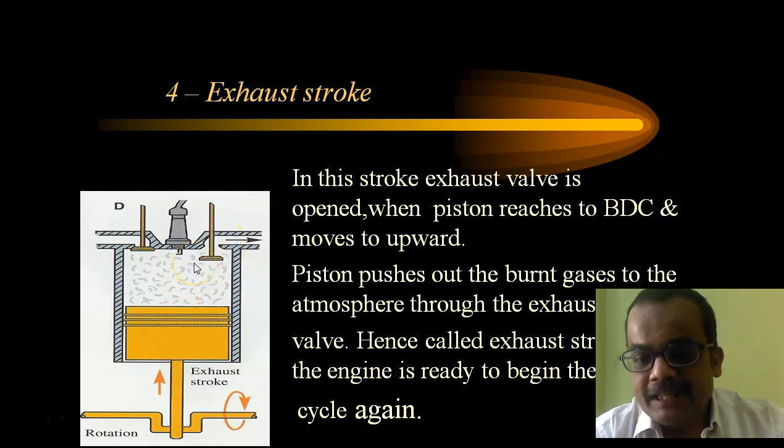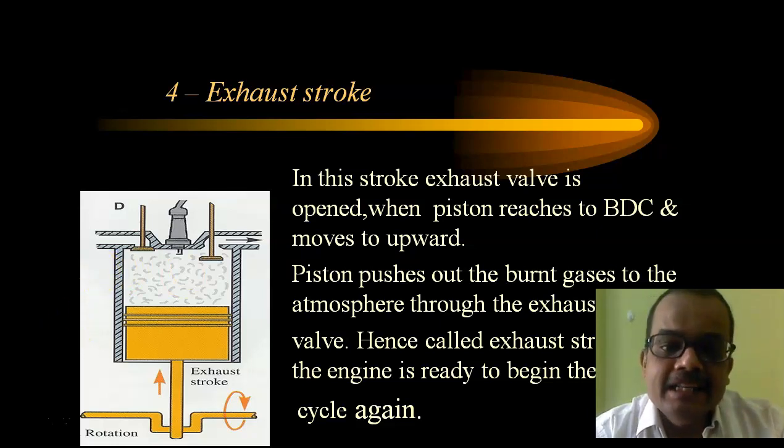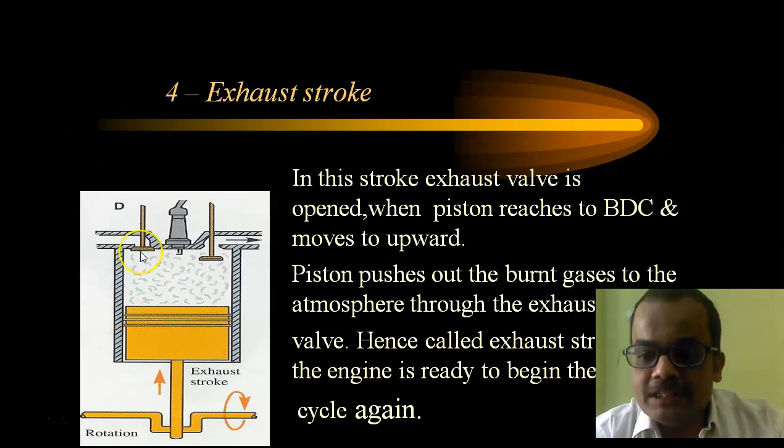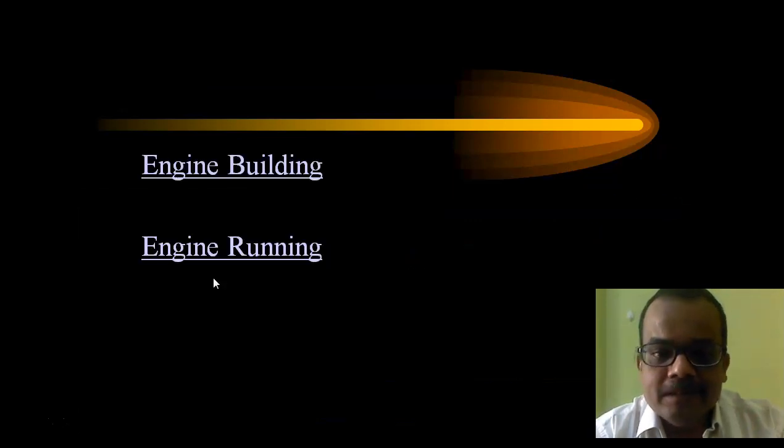So in a suction stroke, the inlet valve is open, exhaust is closed. In a compression stroke, both the valves are closed. In an expansion or a power stroke, both the valves are closed. And in the exhaust stroke, suction valve is closed and exhaust valve is open.